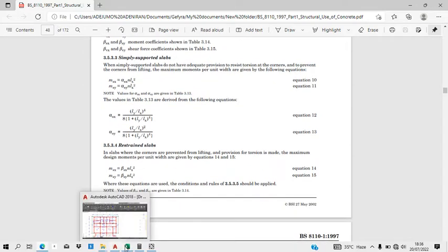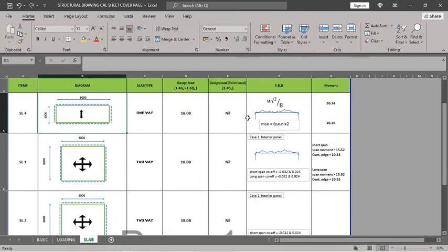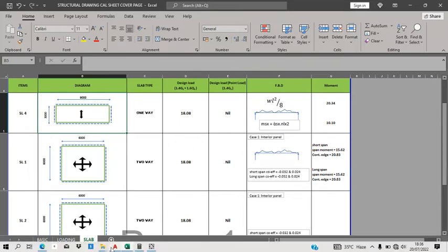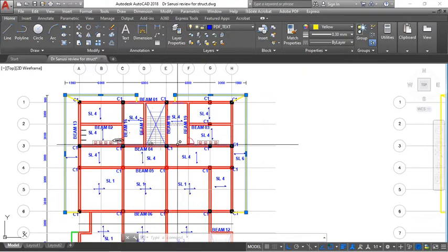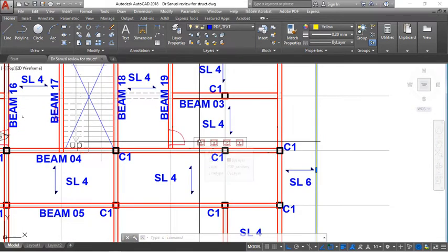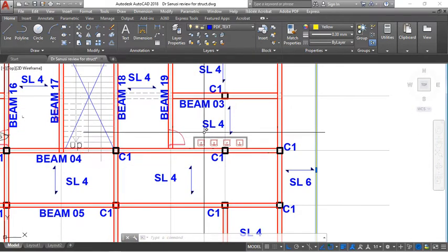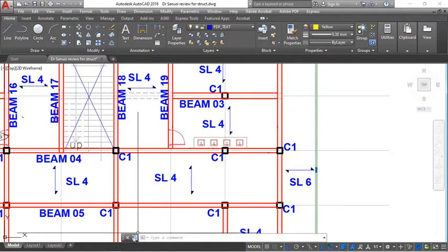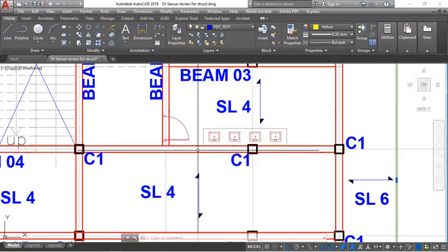So if this particular slab is isolated, then I can use this maximum bending moment, which assumes that there's no moment here, there's no moment here. But in my actual case, there are other slabs adjoining, so that means there's a restraint. Then I will have top bars along all these edges. So in that case, I will have support moment.